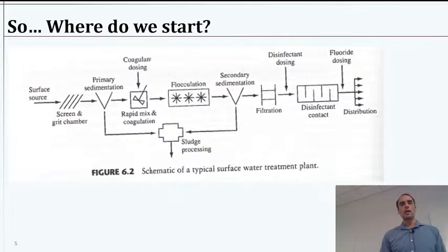For coagulation in particular, it's like adding a chemical and mixing it up really fast into our system. So it's usually a pretty small chamber, rapidly mixed, just to get them together. And then we give them time in the flocculation chamber to let them slowly meet and particles to grow and all that. After we do both of those steps, then we'll go back to sedimentation again. Of course, we don't need to relearn all that, but we'll go through that step again in order to now make use of the better particle diameter, so the better settling velocity, get more removal. Okay? So all of this is piecing together to say, can we do simple things to make gravity work better, to make use of gravity, all that.